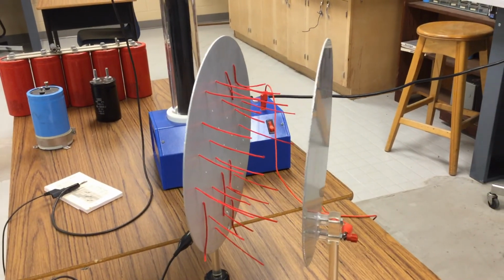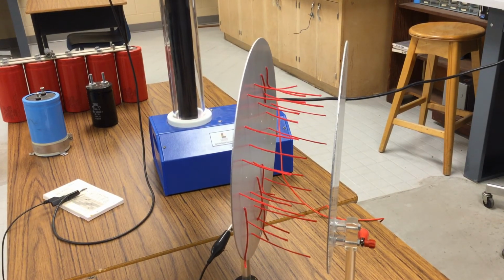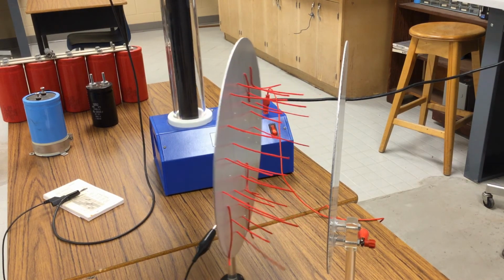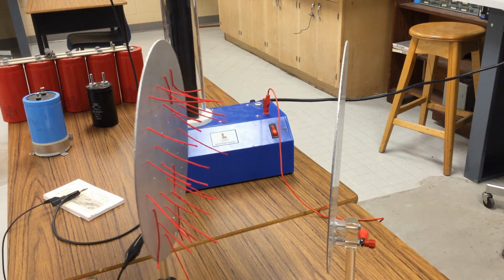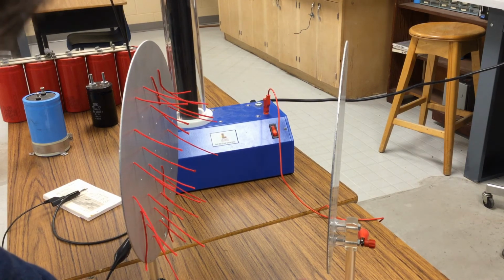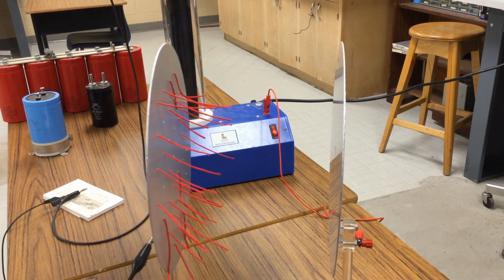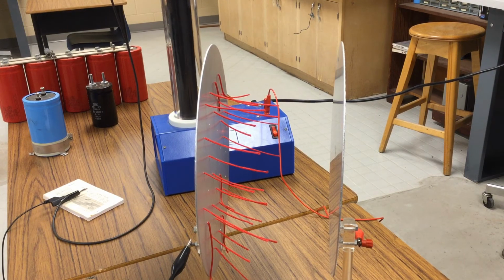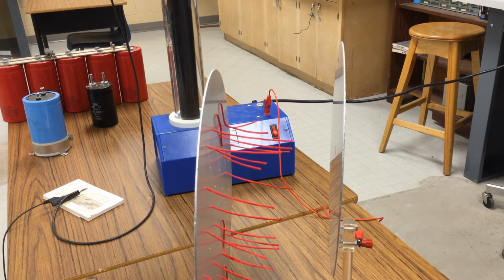So as I move the plates closer to each other, you can see that there's a greater force of attraction because our strings are standing up straighter. As I move the plates away, there's less force of attraction, and they don't quite stand at attention as much. Here, I'll turn this guy a little bit more this way. So one of the things that determines the amount of capacitance we have is the distance between the plates. The other thing that affects capacitance is plate area.